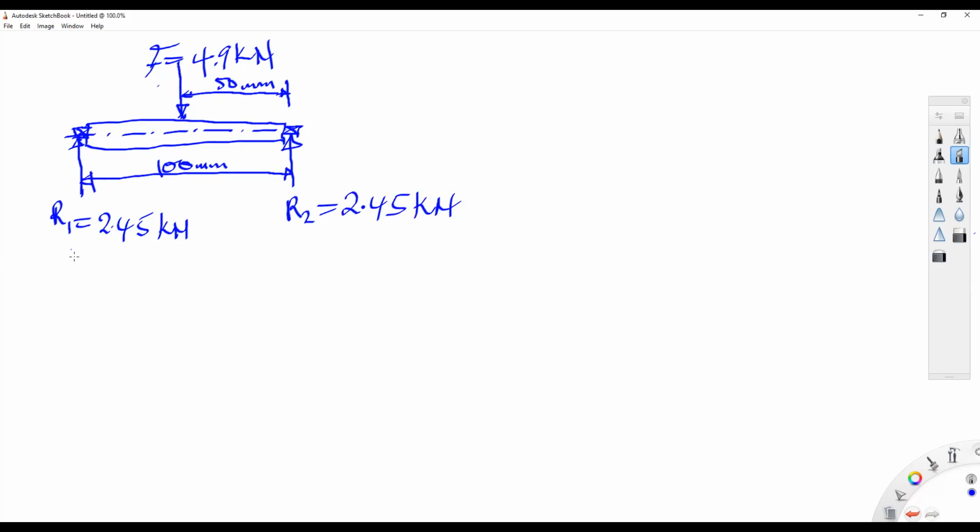And we know that bending moment M will be equal to, in this case, if we take a section along that and want to find the bending moment, it will basically be equal to the reaction. Let me say, if we are taking section at this point, we'll find the bending moment, R1 times X. Okay, so that's the distance.